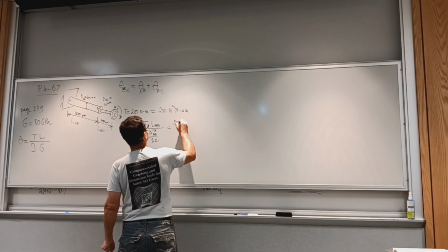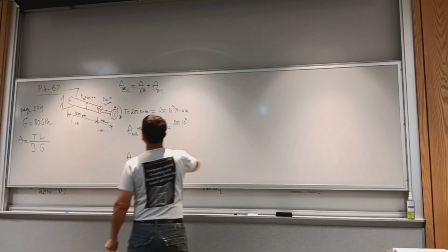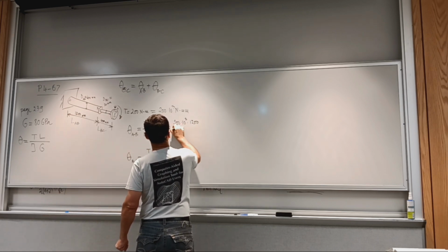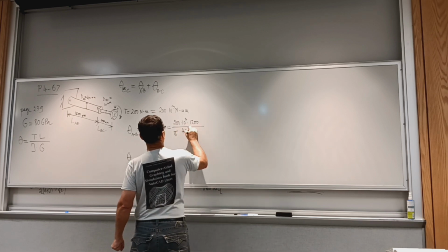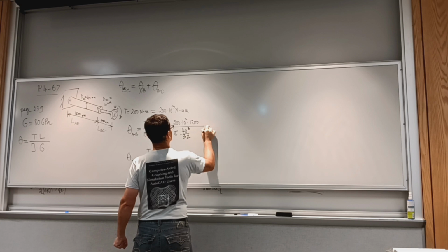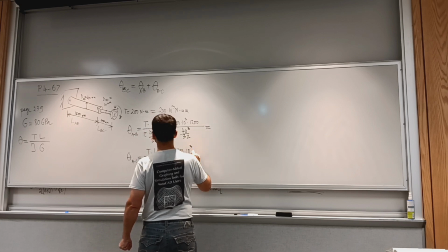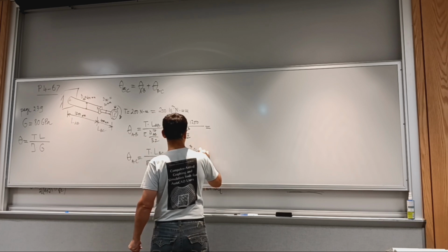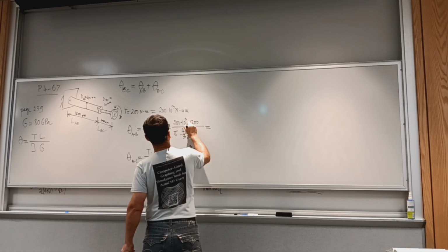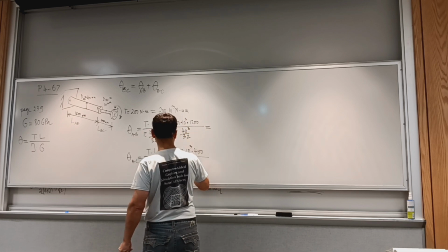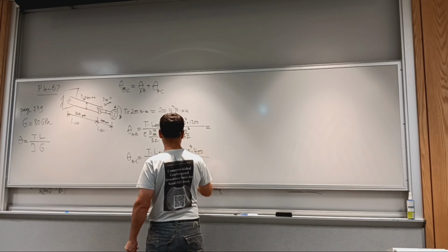So we have 200 times 10 to the power 3 times length AB, 1200, over pi, 40 to the power 4 over 32. And then the second one, same torque, 10 to the 3, length is 400. Okay, and then pi, the diameter is 20 to the power 4 over 32.